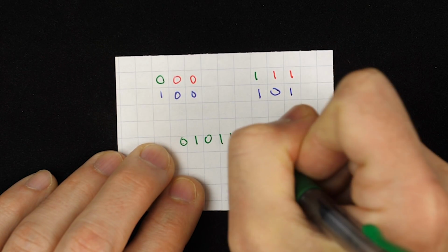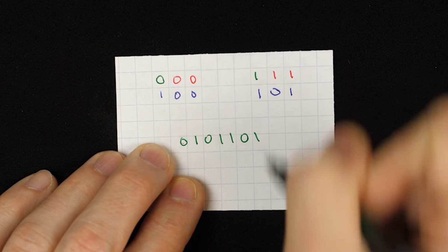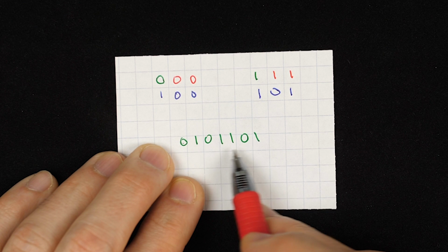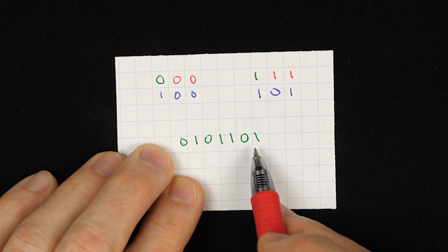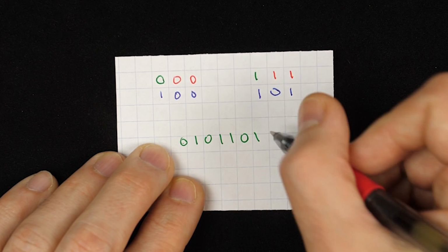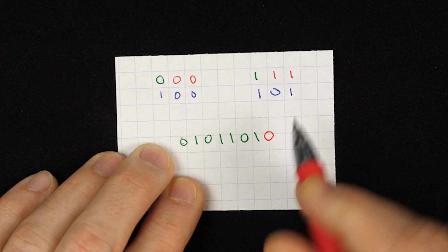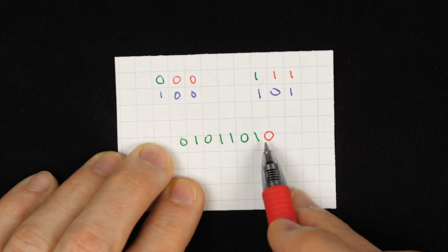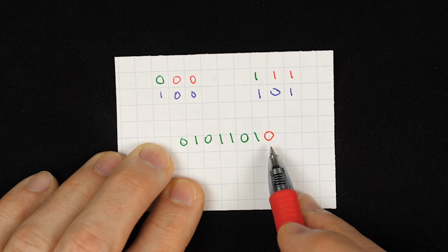I've got some other videos on parity checks, but basically, if you have a bunch of binary data, you can add a bit that will ensure that the data has an even number of ones. So here we've got 1, 2, 3, 4 ones. In this case, it already has an even number of ones, so we could add a parity bit of 0. But if it had an odd number of ones, we could add a 1 to the end so that in total, all of this has an even number of ones.